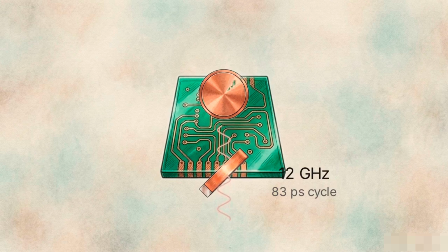When the voltage cycle reaches its negative peak, electrons crowd the tip of the feed wire. This concentration repels the free electrons in the overhead copper patch, shoving them to the far side and creating a severe charge disparity. Because one edge of the patch is now positive and the other is negative, the metal generates horizontal fringing electric fields across its surface.